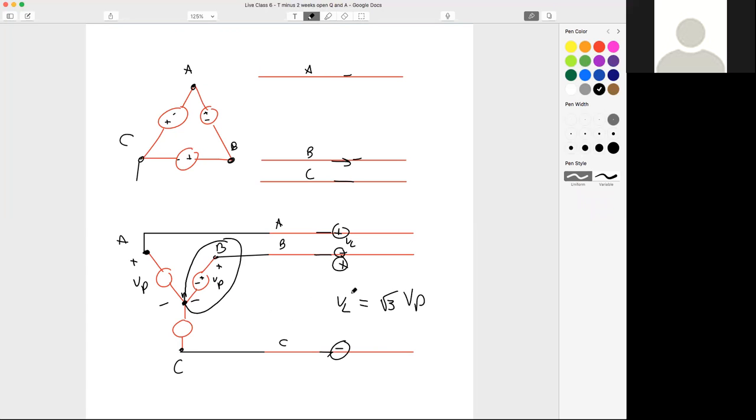When we're talking about line voltage and line current, we're actually talking about either the voltage across two lines or the current flowing down one of them. We can relate what it is to what our phase source is, right? So even though it's a three-phase transformer, if we say 4160 to 480, yes, these are our three-phase line-to-line voltages, because what do we care about? We're using that Y source to transmit the line-to-line voltage that we need.